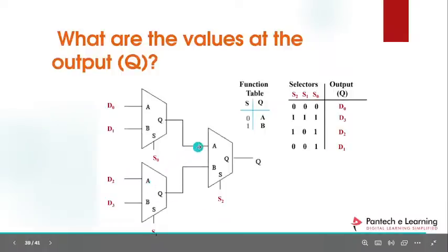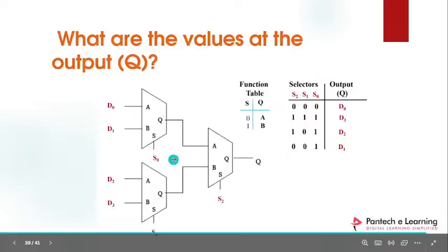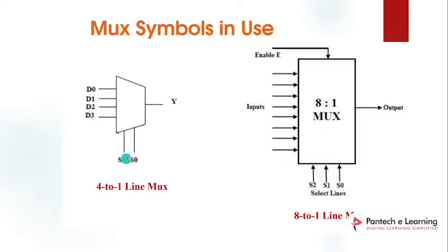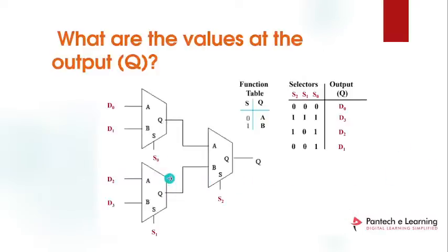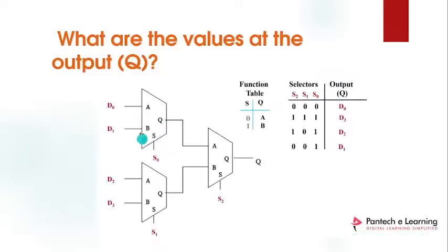And this is a multiplexer we use for making 4 inputs 1 output by using 2x1 multiplexers. We can also get a 4 inputs 1 output multiplexer by using 2x1 multiplexers based on this circuit only. Here I already said, 4 inputs must have two selection lines. In that we have to give selection lines for this mux: S1, S2 and S0. Based on this circuit we can get these output values.